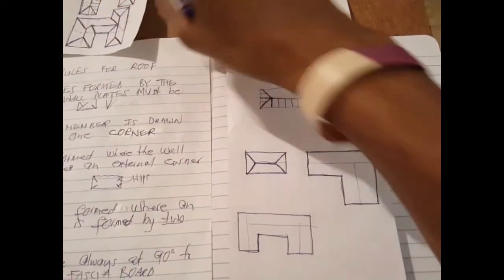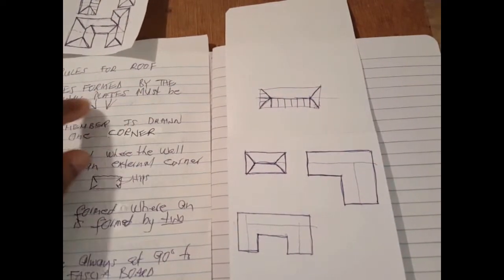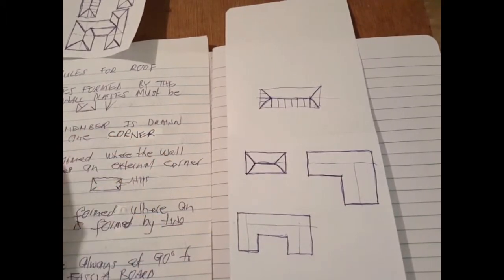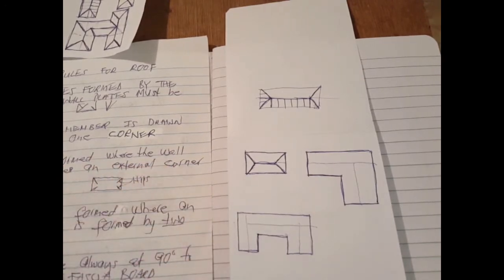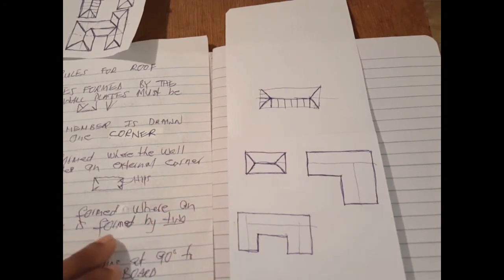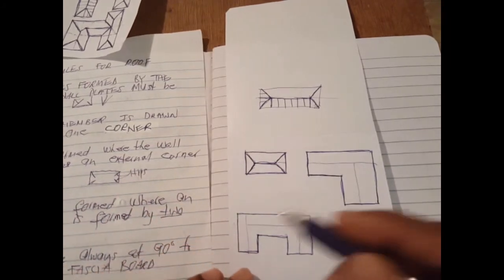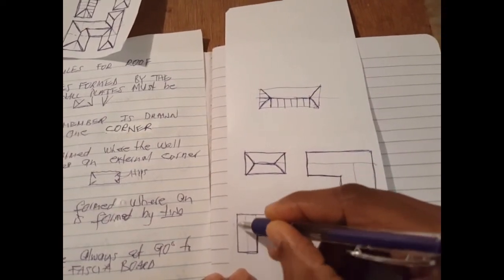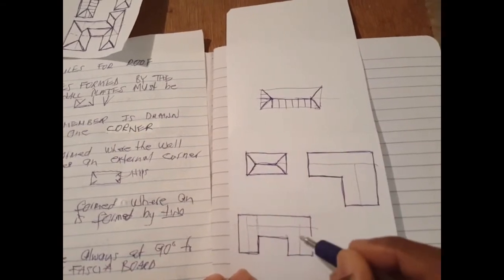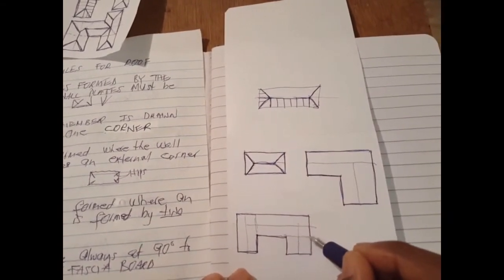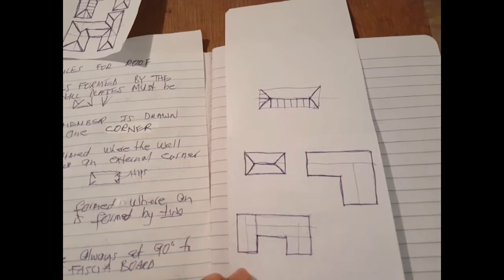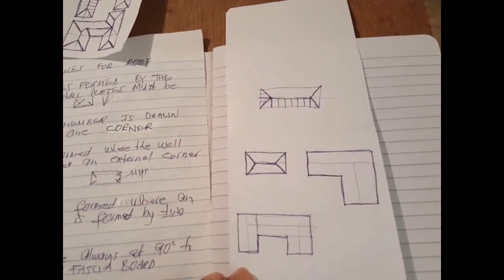Wherein every angle formed by the external wall plate must be bisected. Only one member is drawn from any corner. Hip is formed where the wall plates create an external angle. Valleys are formed where an internal corner is formed by two plates. All right. So for here, again, we must create a rectangle as a first step. So we create one rectangle there. We can go ahead and create another rectangle here. Another rectangle here. So these are what will be used to generate our roof, right?